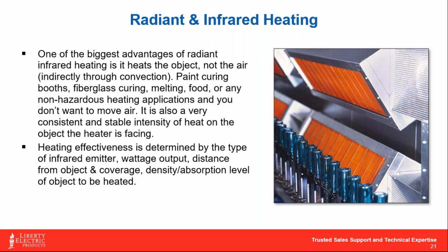And again, the heating effectiveness of this is going to be determined by what wavelength you're using, how much wattage, and the distance from your heater to the object that you're trying to heat. One other factor that is important to mention about these is the absorption level of the object you are trying to heat, because some objects will reflect a portion of that infrared wave, and some of them will just soak it all up. So obviously our heat transference is better with objects that absorb it, and we have to compensate when we're talking about reflective objects.